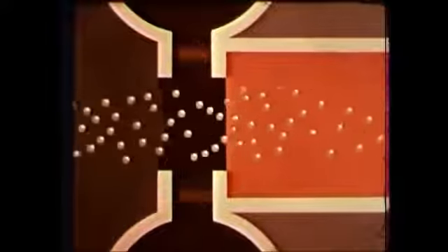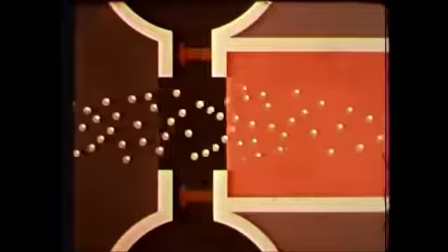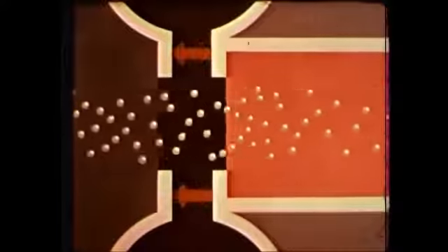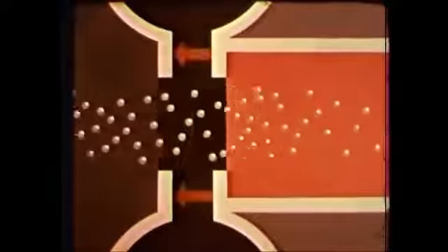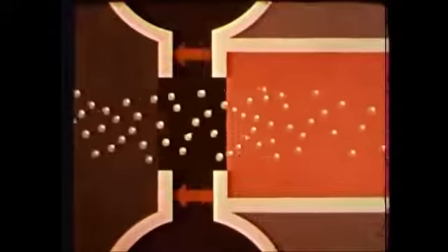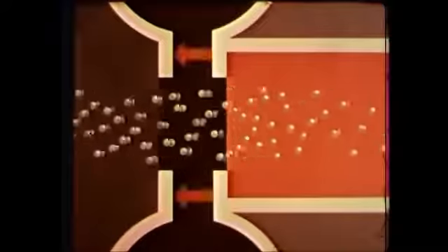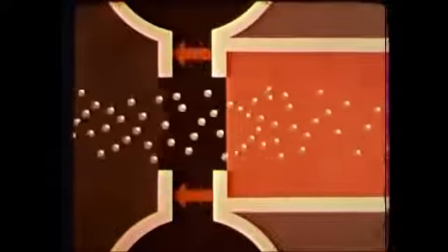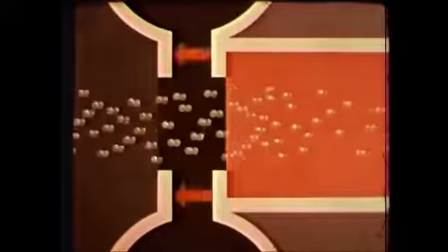A constant stream of electrons enters the first resonator so that almost equal numbers will be accelerated and decelerated. Thus, the average kinetic energy of the outgoing electrons is nearly equal to the energy of the incoming electrons, and almost no energy is taken from the field of the cavity.